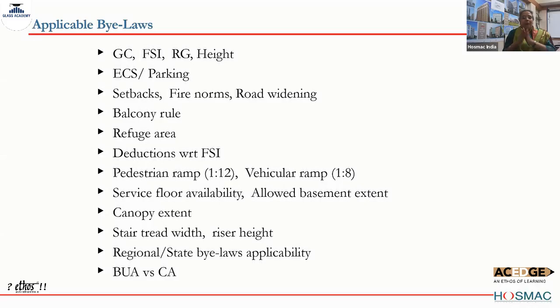Because the spans of a hospital are huge, the beam is going to be deep. Flat slabs, PT slabs are not built for hospitals anymore in India. There is a national disaster code for the same. We do not build anymore. We used to build 10 years ago, 6 years ago. But in the last 5 years, the code is not allowing you to build flat slabs or PT slabs for hospitals. So we go back to beam column structure. And because of beam column structure, we have to have higher floor heights. We will discuss this later.